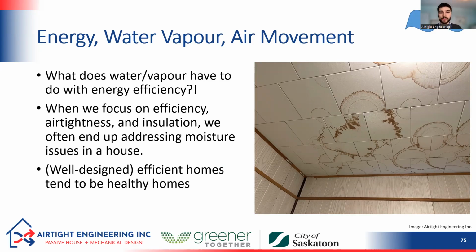Okay, let's talk a little bit about water and humidity movement. So what does this have to do with energy efficiency, you might be wondering? Heating balance, it's really obvious what that has to do with energy efficiency, but what about water vapor? Well, the interesting thing is this is actually kind of an effect of energy efficiency. Often, when we focus on improving the efficiency of a building through further airtightness, through more insulation, we end up addressing moisture issues that are happening in a house. So a well designed, efficient home should also become a healthier home with fewer water issues.